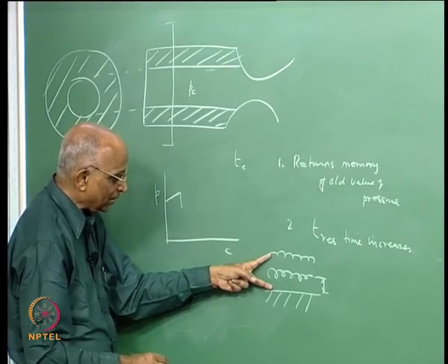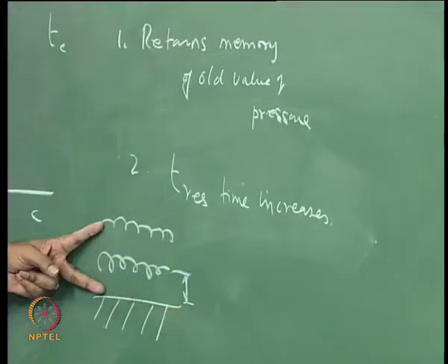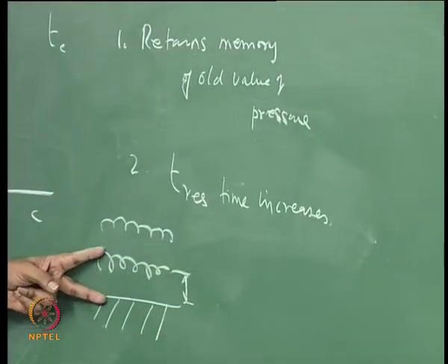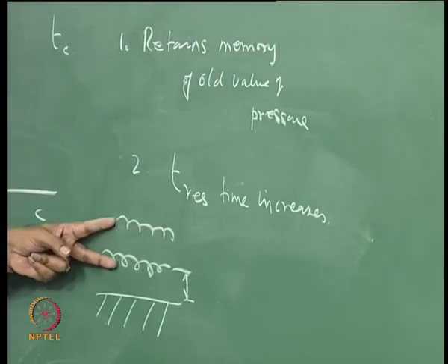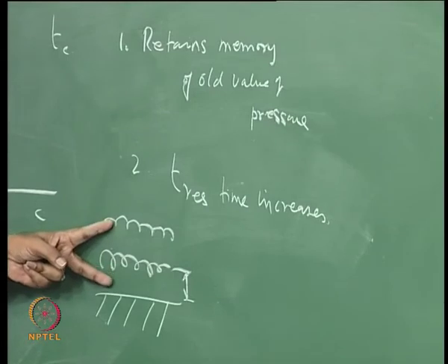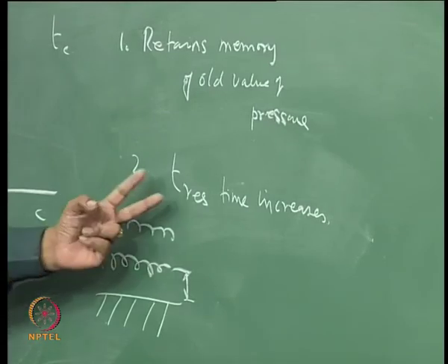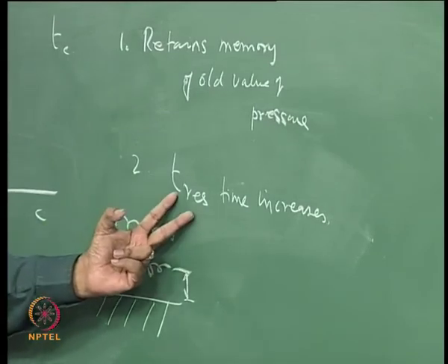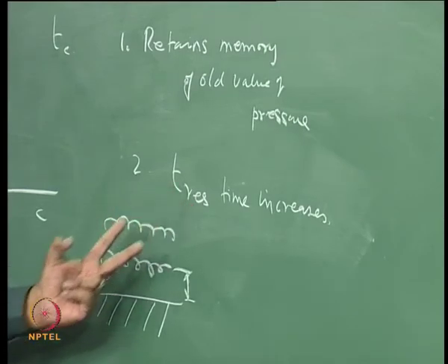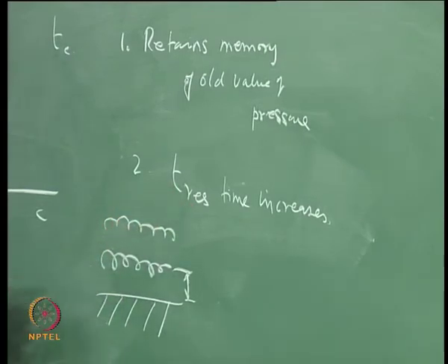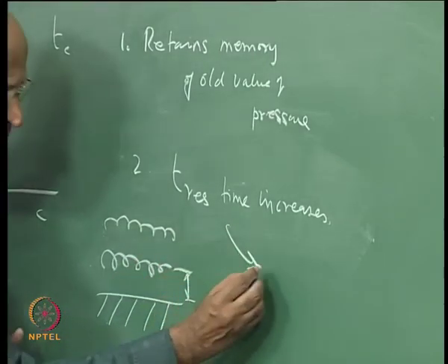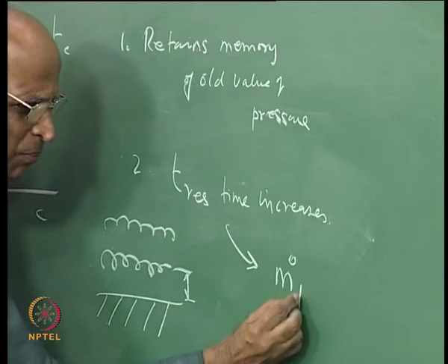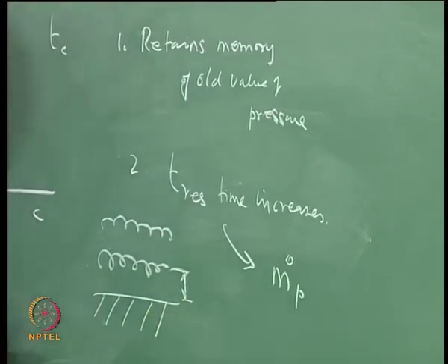If pressure has decreased, the chemical reaction rate has decreased. If chemical reaction rate has decreased, the rate at which mass of the gases is getting generated has decreased, the velocity has decreased. If velocity has decreased for the same distance, the residence time has increased. If residence time has increased, the time for chemical reactions to get completed is available, therefore residence time increasing results in more value of the rate of mass generation.